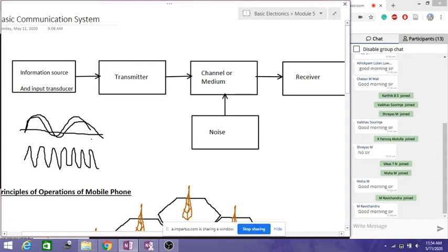That is why we put this signal on the carrier signal. That process we call modulation. With the help of modulation, we can transmit this signal to a longer distance with shorter antennas, because frequency and wavelength are related by the formula lambda equals C by F. So frequency and lambda are inversely proportional to each other, and the speed is determined by the speed of light, that is 3 × 10 to the power of 8. Now there are different types of modulators: a frequency modulator, an amplitude modulator, or a phase modulator. This is about the analog modulators.